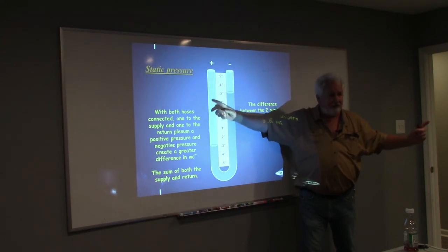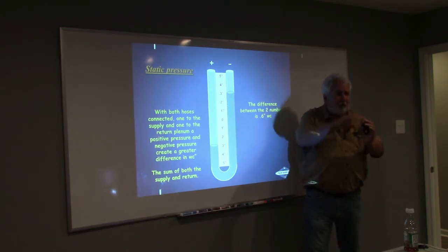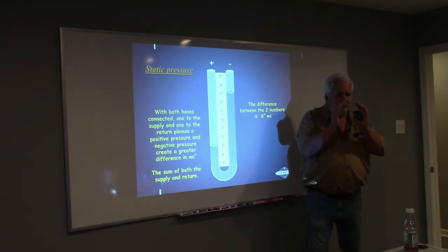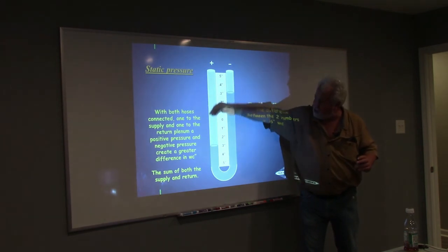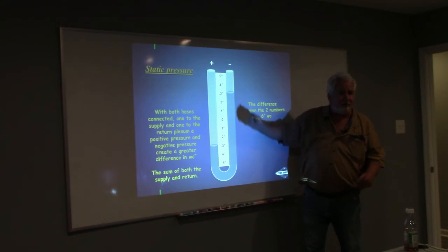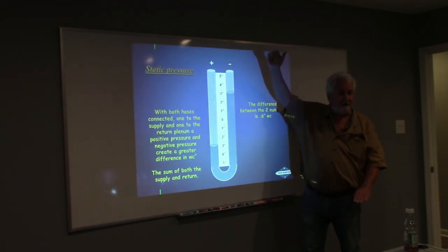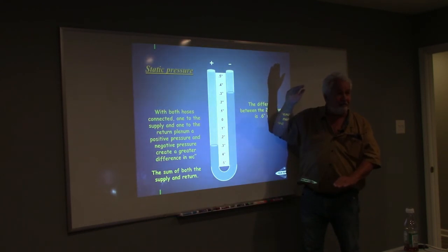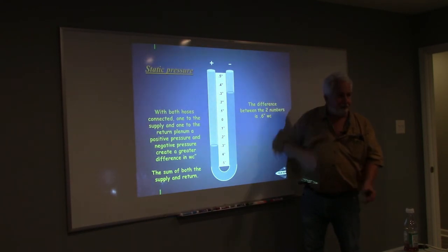If that supply air static was very small ductwork, or all kinked, that blower's trying to blow through there. What's happening to the static? It's blowing so hard down here, it's pushing this one way up. So my external static pressure is getting higher and higher. Does that make sense? And we said as the static increases, what happens to CFM? It goes down. Good. That make sense?